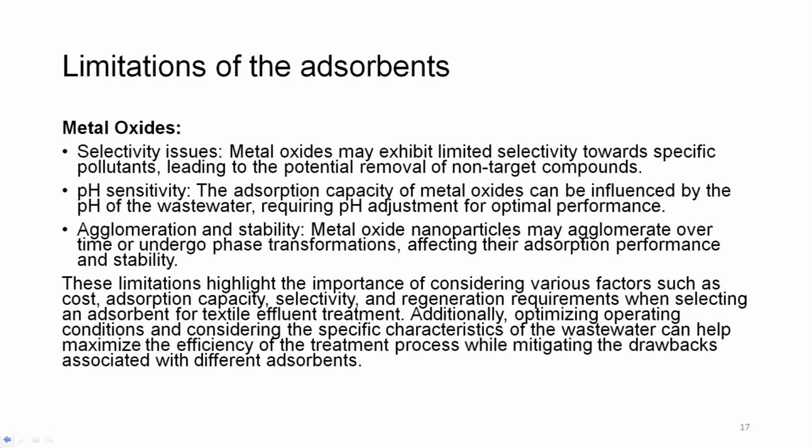The adsorption capacity of metal oxides can be influenced by the pH of the wastewater, requiring pH adjustment for optimal performance. Agglomeration and stability. Metal oxide nanoparticles may agglomerate over time and undergo phase transformation, affecting their adsorption performance and stability.